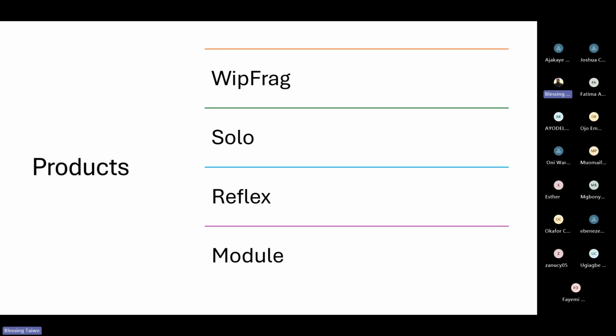So we have a system that is capable of capturing pictures from the truck right from the beginning, when it arrives at the crusher hopper, till the truck is done dumping the material. The camera can take pictures per second depending on the timing you set, and do the analysis instantly. So then the Solo system captures material on a moving conveyor belt. Then the module is a system that you can use to send commands based on the material analyzed. So you can set an if statement that when the size is at this stage, close the crusher, set an alarm and the like. That's what the module stands for.